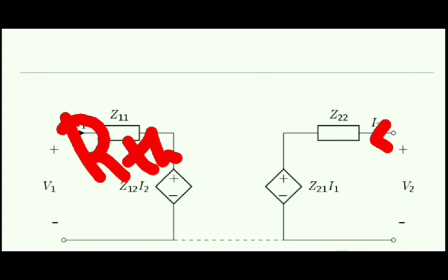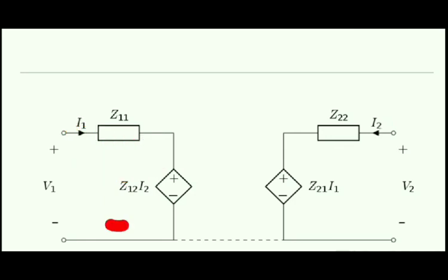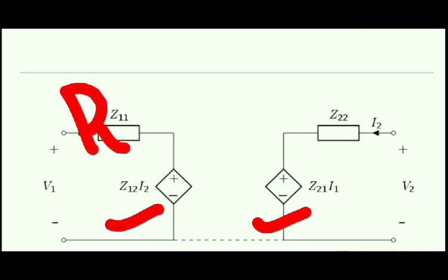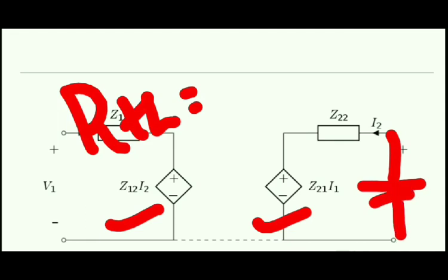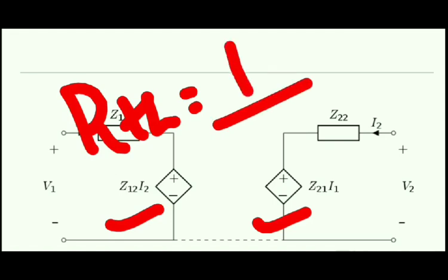But when a circuit will have dependent sources like over here you just see this one and this one, the procedure to solve the R Thevenin is basically to place a battery source of 1 volt, and with respect to I2 current we will form a ratio like this. This is the battery source of 1 volt, and with respect to the current I2 which is delivered from this 1 volt battery.